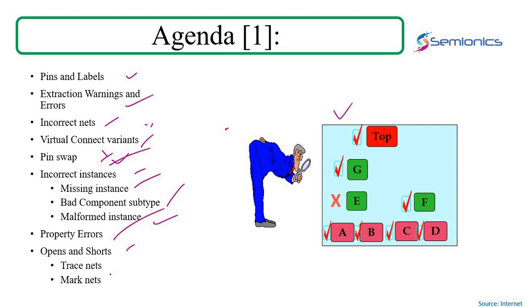But along with that, you should also learn in this session what trace nets are. Whenever you're trying to debug a short, you will use some features in the tool. How to use these features, how to use mark nets. If there is a very big design and you don't know where the short is, the short net is running through and through, what techniques should a layout engineer use? Or how do you figure out at what level of metal the short is happening?